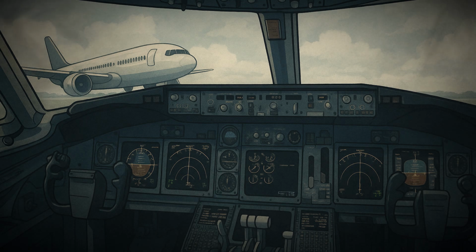Future technologies continue to focus on reducing drag further. Concepts such as laminar flow wings, which maintain smooth airflow across a greater portion of the surface, promise significant efficiency improvements. Adaptive surfaces that change shape in response to airflow, inspired by bird wings, may also reduce drag by optimizing lift and resistance simultaneously. Alternative propulsion systems such as distributed electric propulsion, which uses multiple smaller engines spread across the wings, can reduce drag by integrating thrust with aerodynamic surfaces more effectively.